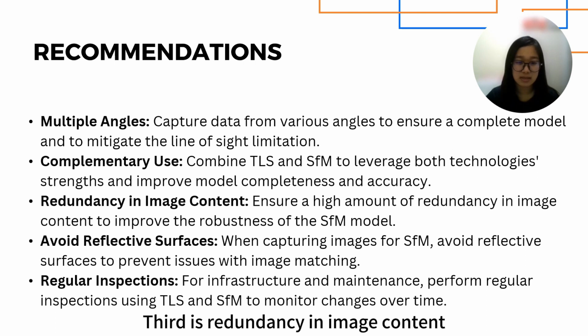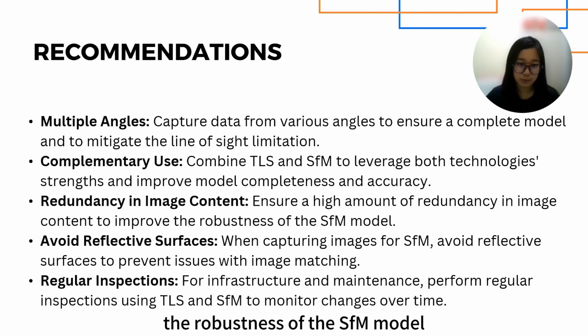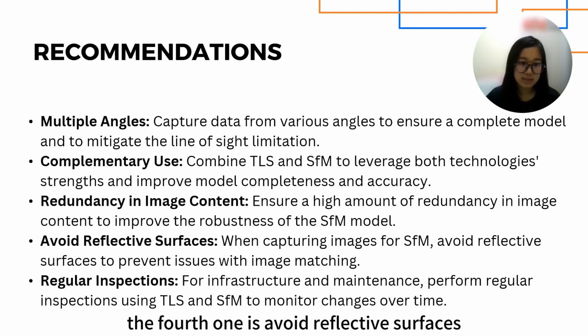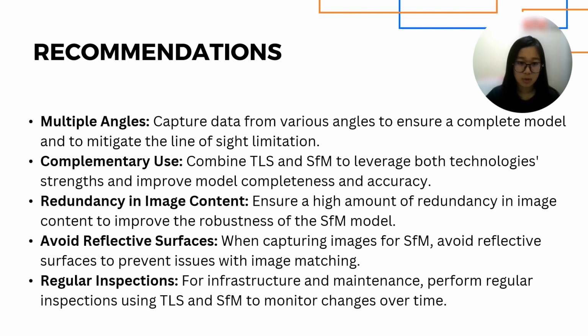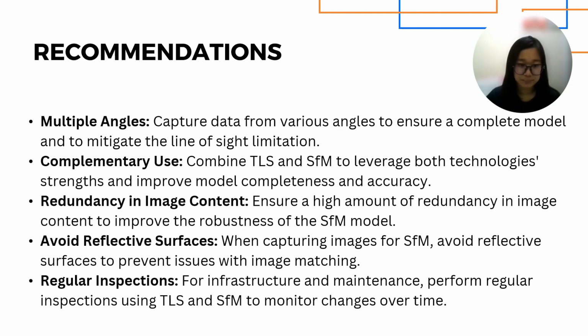Third is redundancy in image content. Ensure a high amount of redundancy in image content to improve the robustness of the SFM model. The fourth one is avoid reflective surfaces. When capturing images for SFM, avoid reflective surfaces to prevent issues with image matching.